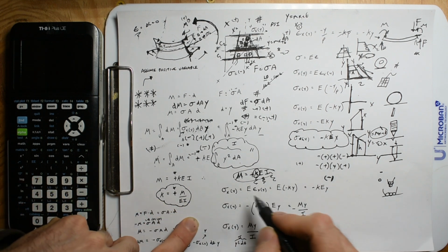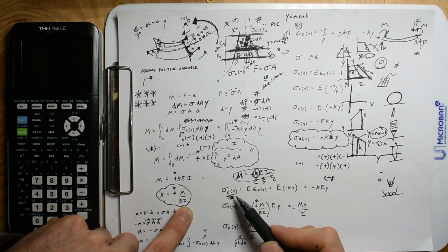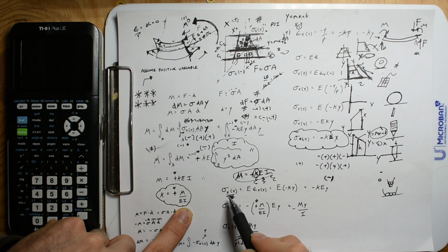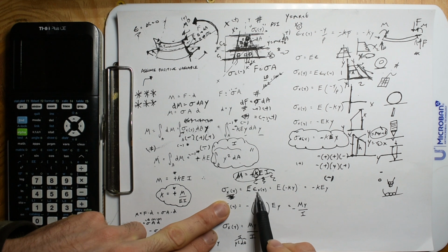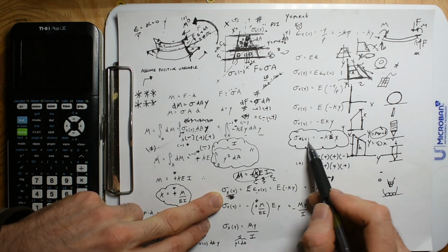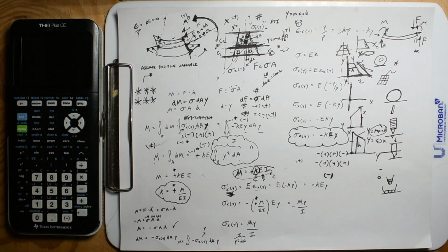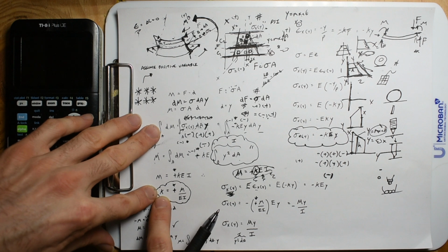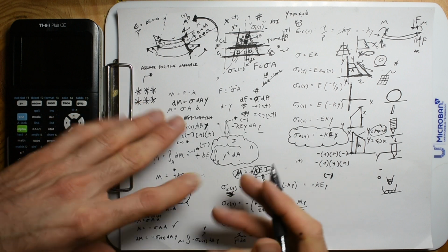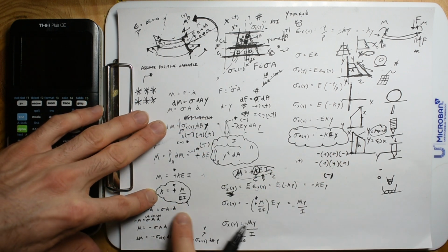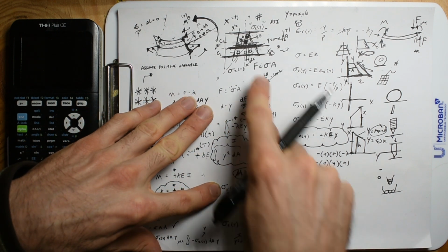And then we go, it seems redundant or weird, but you go back to your strain, your strength equation, your stress. And stress is equal to modulus of elasticity times strain. We said this is equal to negative Ky. All right, last push. Yeah, so we get this relationship between curvature, the moment, the shape of the material, and the material itself, the stiffness, the properties, and then we can throw that value for curvature into the axial stress equation.